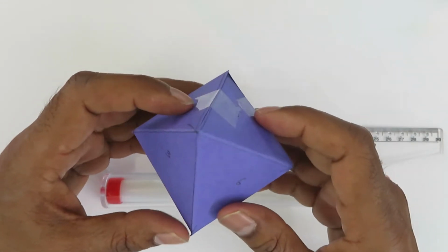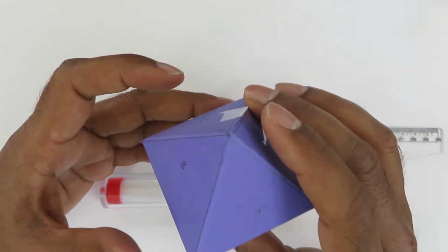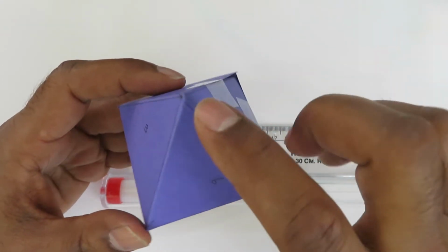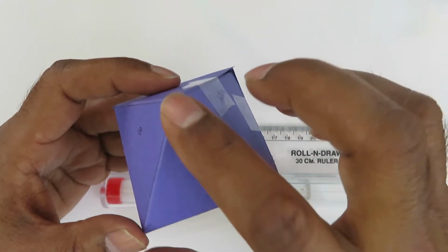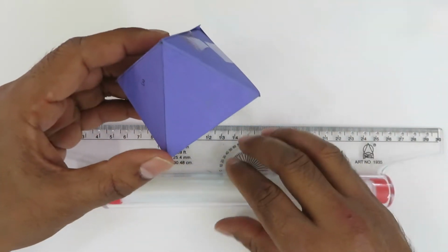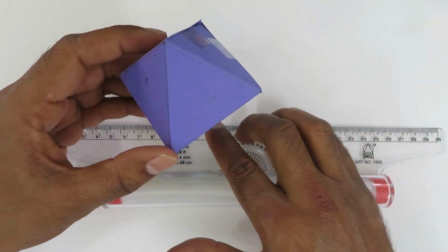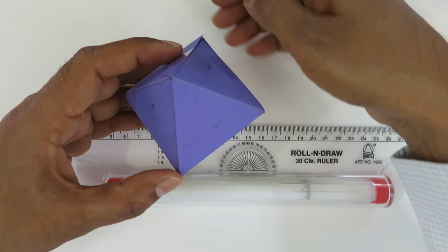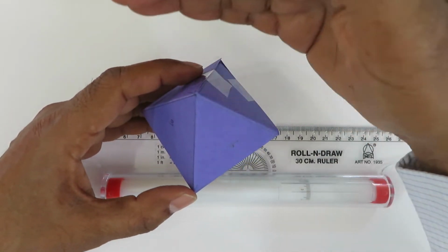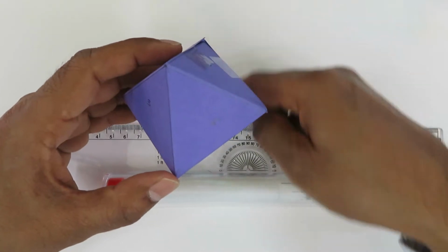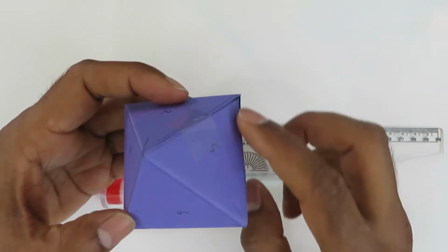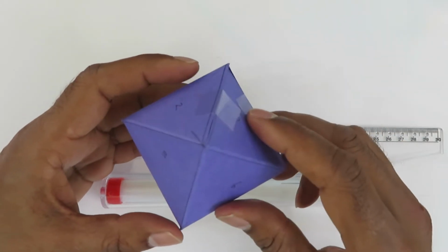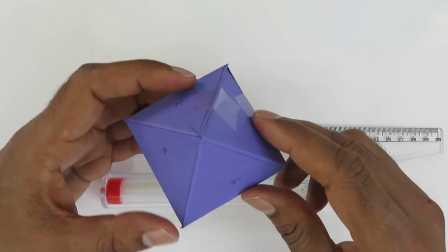So the problem says that a regular octahedron has one of its axes of symmetry vertical. So let's say this axis, we call it OP, is vertical, and one of the vertices, this vertex, is on the HP. This vertex is 60 mm from the VP. So if we imagine VP is here, this vertex is 60 mm from the VP. All the edges are 40 mm in length. So we will draw the top view, the front view and the left hand side view in the first angle projection.